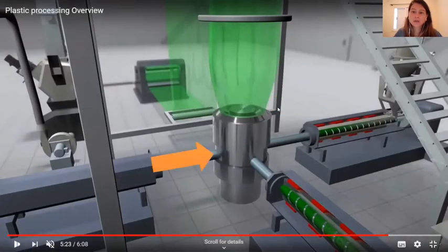In this video, I presented different extruders. The simpler process only uses one extruder in order to create the plastic bubble. In the other case, various extruders are used in order to obtain a bubble composed of different layers, so different polymer compositions. Each extruder processes a different composition.